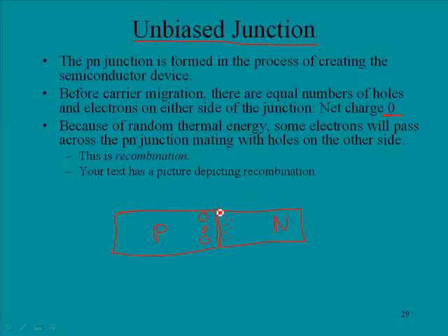Now, when we bring them together, something occurs. The electrons here, now these are free electrons, remember, they see that available hole over there. And so the free electrons are going to move over to those holes. Now what that is going to do is, since this material on the N side is losing an electron, this will result in a net positive charge on the N material.